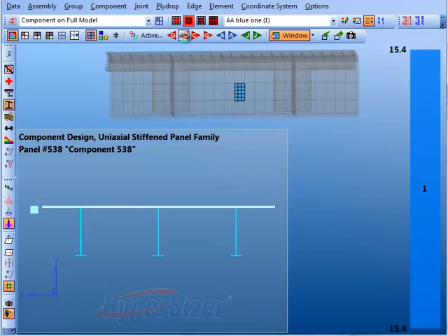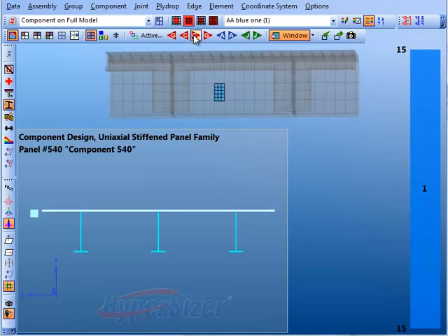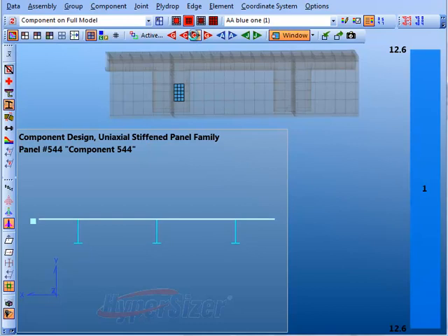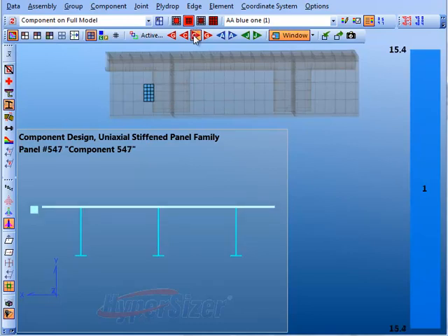The resulting designs are sized to carry the computed FEA forces, and though the forces are representative of ship loads, they are dependent on the FEM approximated applied external loadings. Therefore, the HyperSizer computed optimum plate thicknesses may be thinner than actual production hardware, while also not meeting standard minimum gauges.